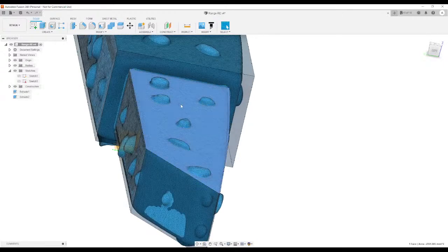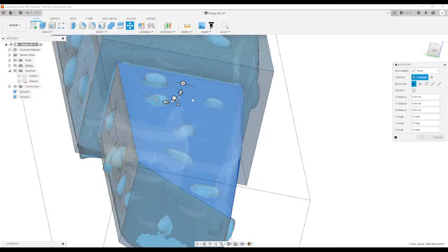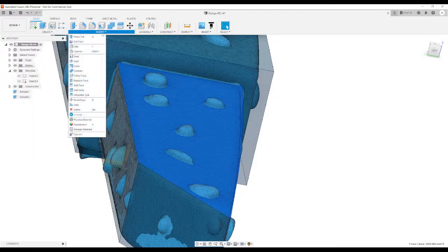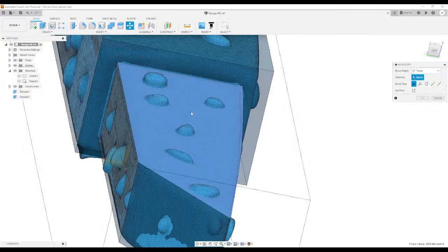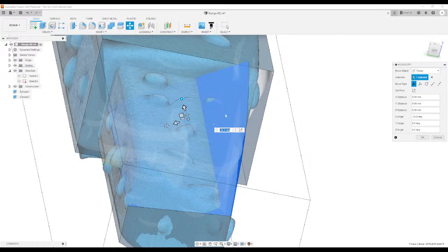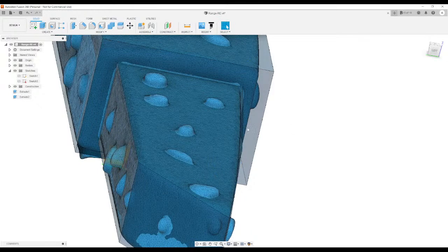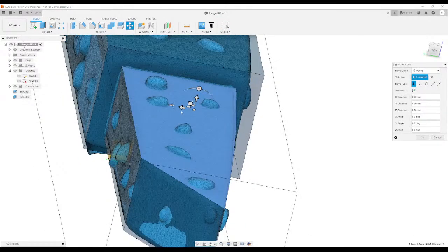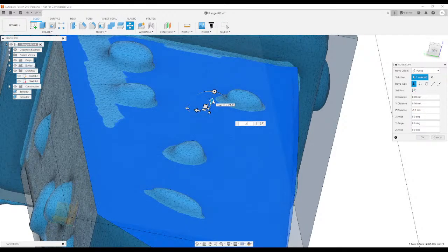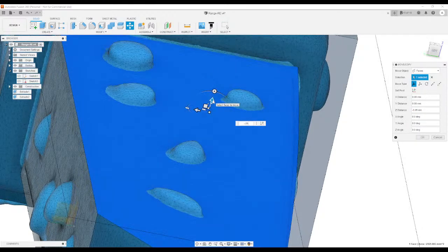The first thing we should do is just try to move the faces, and basically if you select the face and press M, or if you select the face and go to modify, move, as you can see there, M, you can move this face or even rotate it according to the pivot point that you have selected. So select face, move, and let's just make sure it's the right size. Minus 0.1, minus 0.05, 0.07, 0.08.